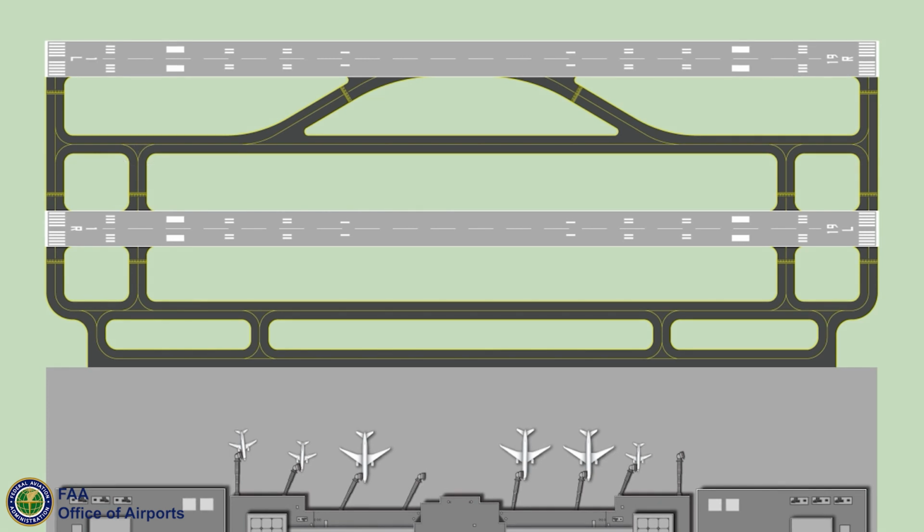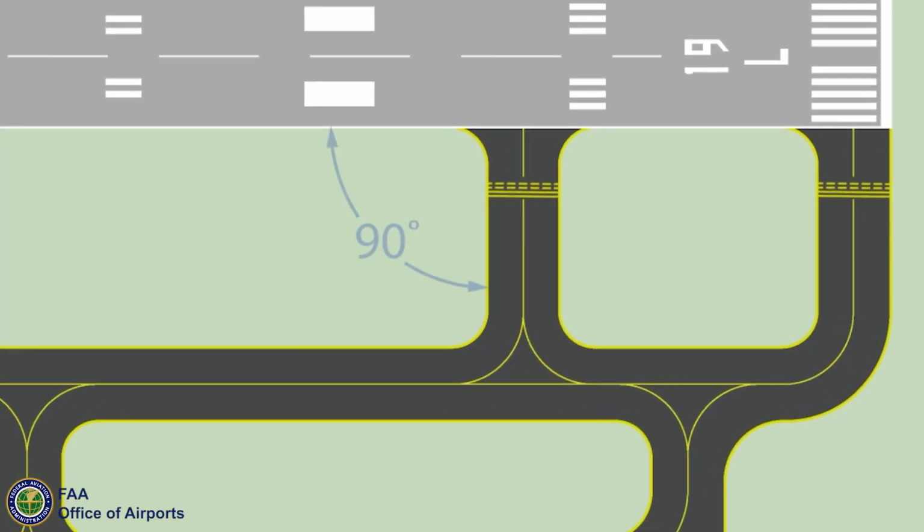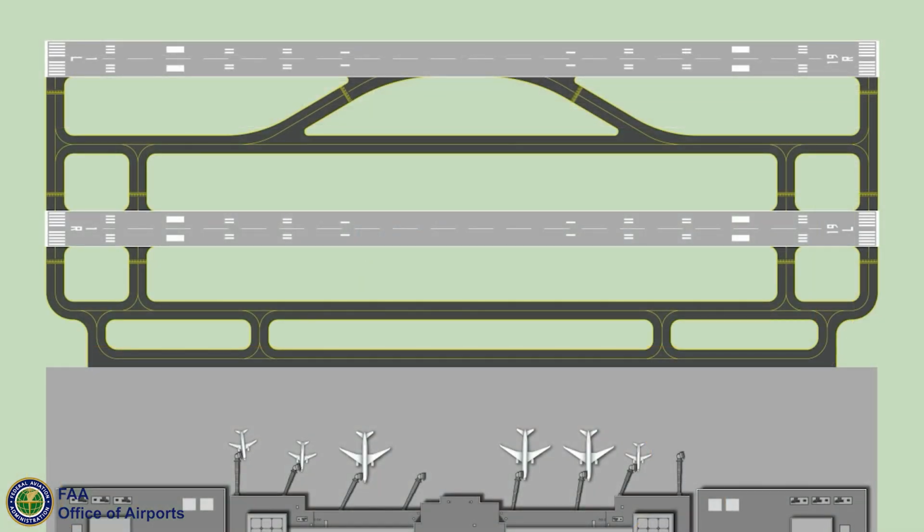This schematic airport layout plan shows several best airport planning practices that help prevent runway incursions. As discussed in this video, the optimal airfield layout provides 90-degree runway taxiway intersections, eliminating direct access from the aircraft parking apron to the runway, and providing a full-length parallel taxiway to prevent using the runway for taxiing when there is no parallel taxiway and prevent direct access from one runway to another.